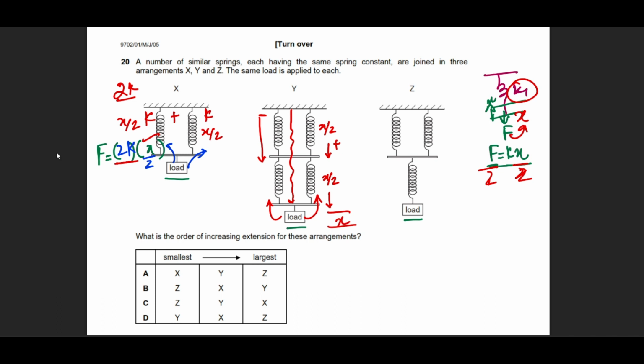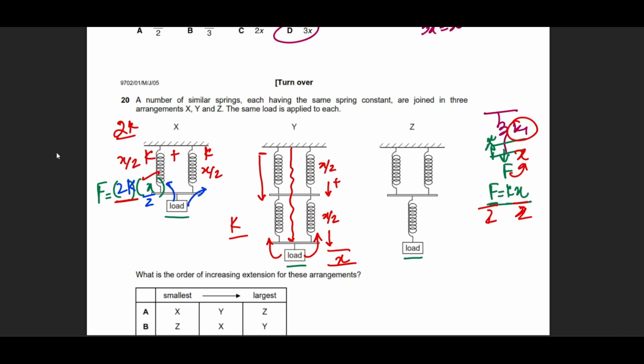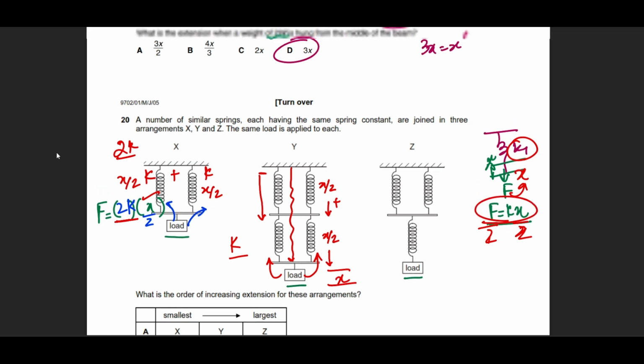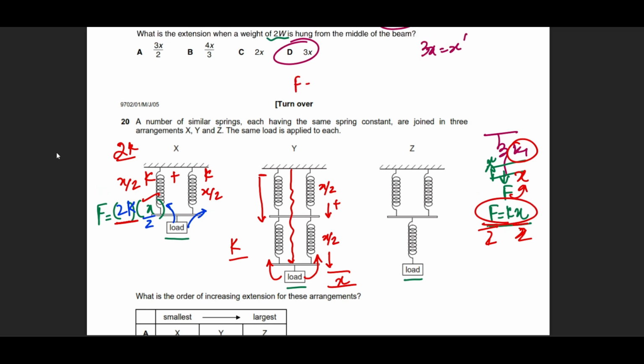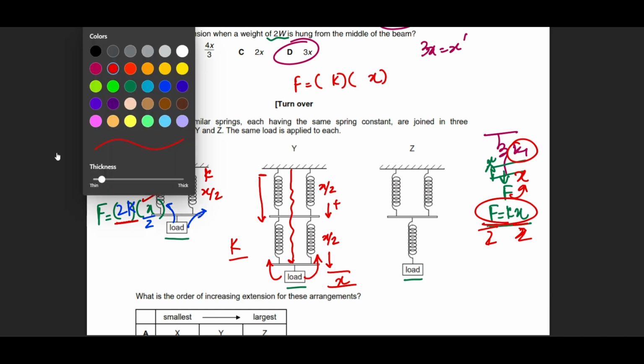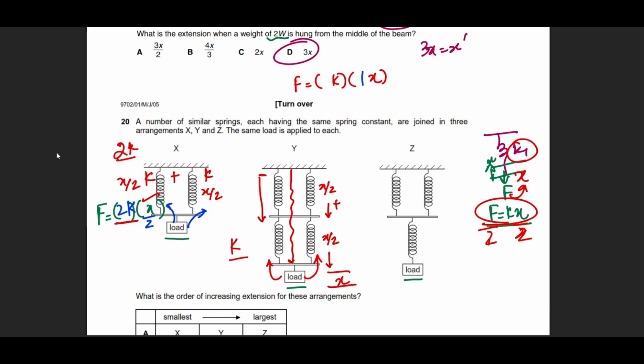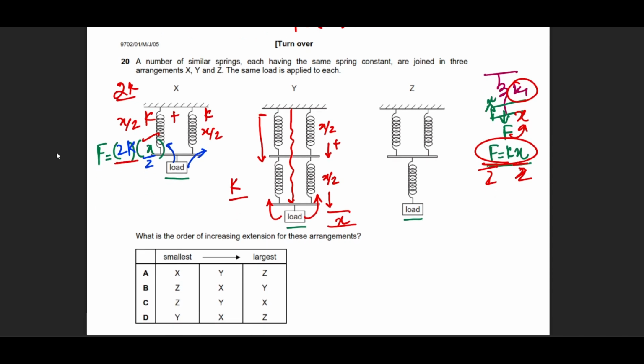And if you want to calculate the spring constant in this situation, the overall total will actually be K. How did we get this? The target is to make F equal to Kx. So F is equal to what should be the value of K if the extension is X. Luckily, over here, the extension was already X, so the spring constant K will also be 1. A shortcut for this is to take the reciprocal of the extension. I'll show you how that looks. In this case, the extension is X by 2. Over here, the extension is X, right?